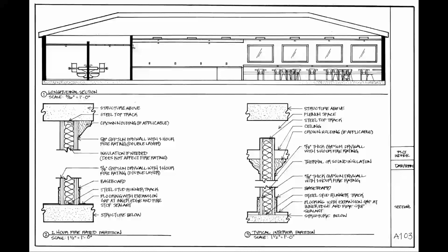So when you draft this, be sure you start off with your very thinnest line weight pen, and then come back in for change of plane with the thicker line weights for the other elements. But just for these, even though technically they are a change of plane, you won't be able to do it with a 0.3 millimeter. You're going to have to do it with the very, very thin ones.